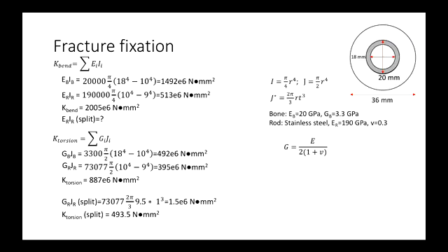But we don't have a circle, we have a tube. So what you can do is say that the inner circle is negative second moment of area. So then you can put I equals pi on 4 r outside to the 4, subtract pi on 4 r inside to the 4.